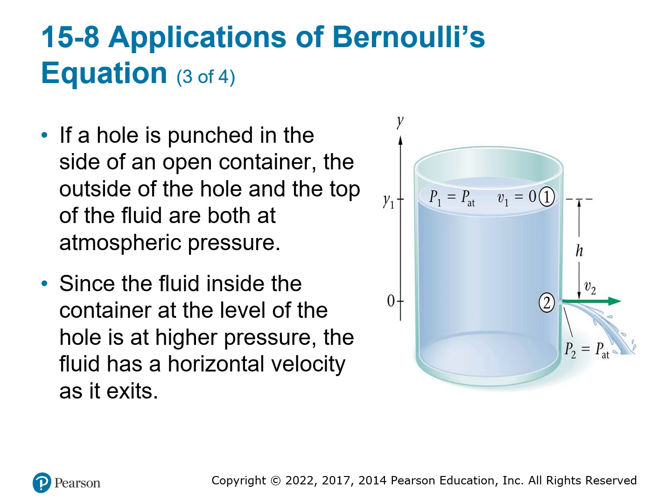Okay, this example is more common with Bernoulli's applications. So if you have a giant cylinder of water that has an open top, then at the top of the fluid, you have atmospheric pressure, right? It's exposed to the atmosphere. But then if you poke a hole on the side of this giant cylinder, then the very top up here is subject to the atmospheric pressure. So the pressure at the top is atmospheric pressure, and the pressure at the hole is also atmospheric pressure.